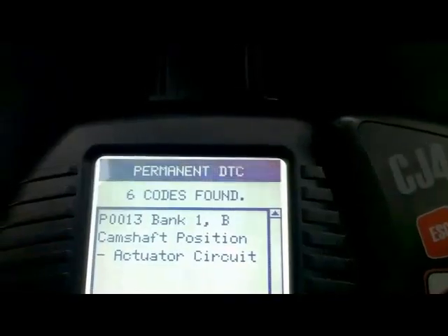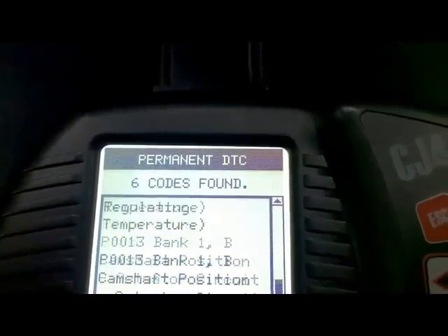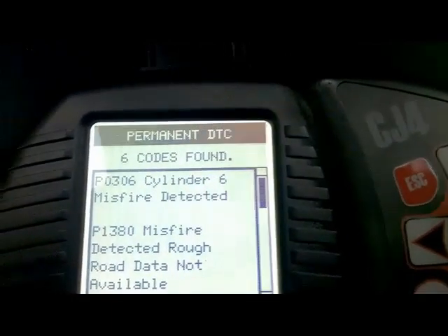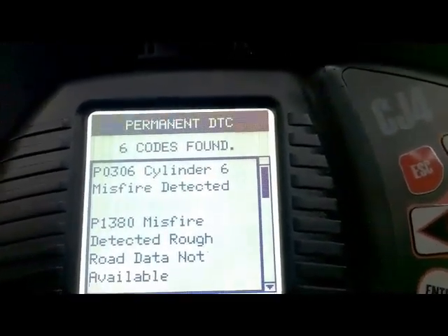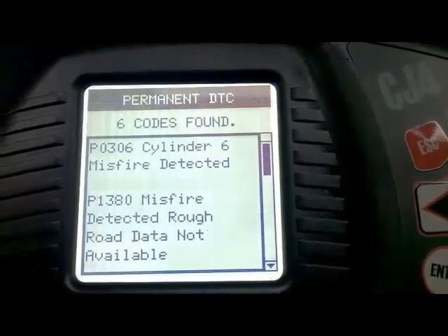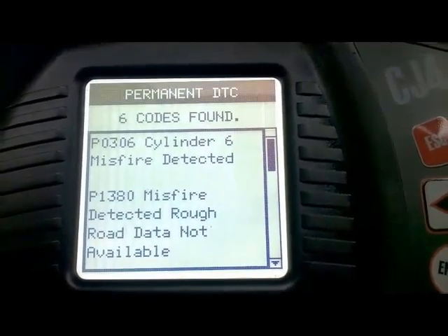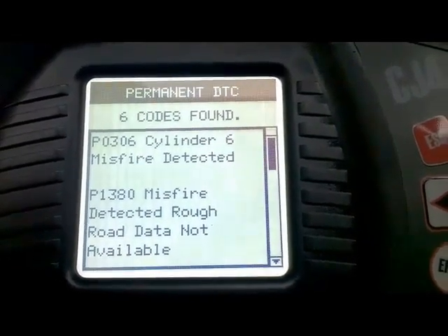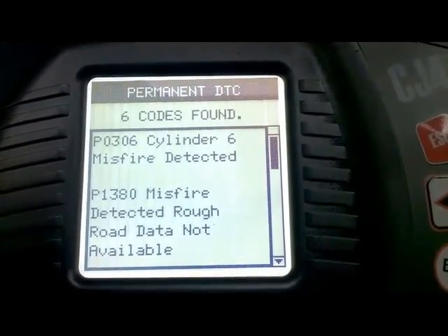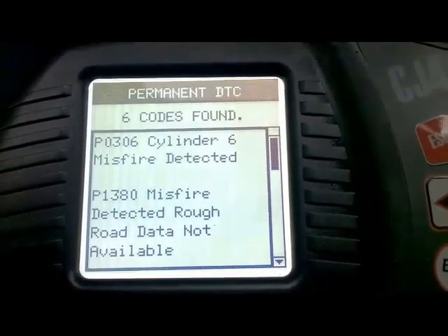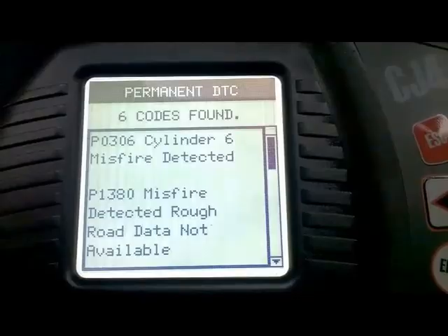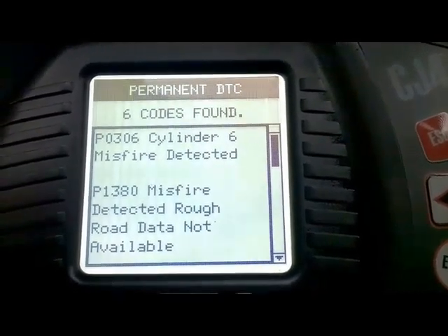All right, guys. So after troubleshooting the last 2 codes, I will then probably go after the P0306 cylinder misfire code. Actually, the customer gave me a brief history that the injector on cylinder number 6 was replaced already, but the code P0306 keeps coming up, and he also has replaced the spark plugs a while back. The only 2 things remaining that I could think of is to probably check the coil pack and perform a compression check on this cylinder number 6. I will only perform these checks if the P0014 was not the root cause of this P0306 misfire code.